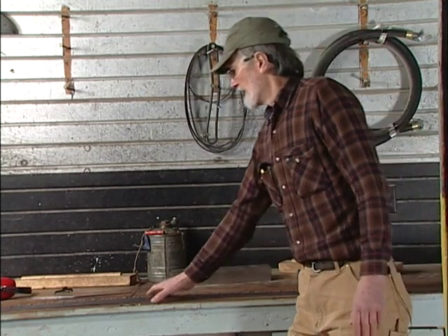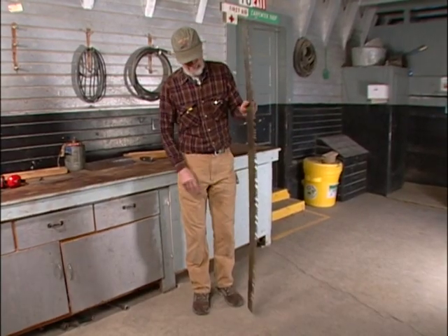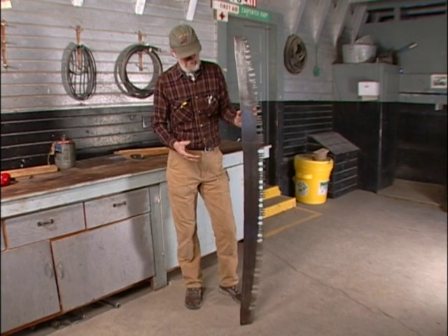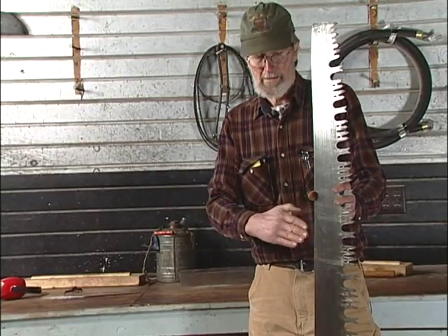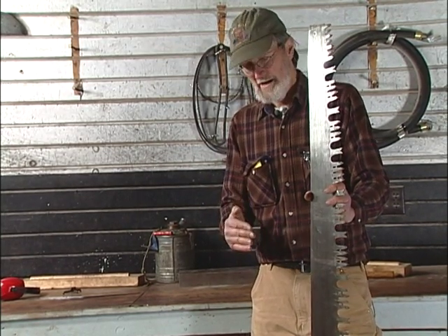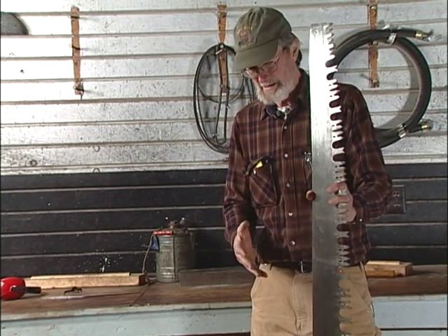Once I've cleaned the saw, the next step in the process is straightening the saw. And you'll find that a saw, even from the factory, is not completely straight. And we want to make sure that it is, because if the saw has a little bit of a kink in it, as you run it through the kerf, a little bit of a kink or a bump in there is going to cause friction in your kerf and will cause the saw to run roughly and bind.